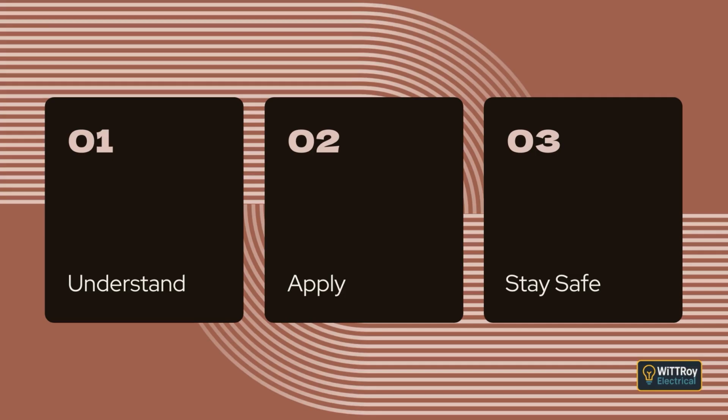Clause 3.9.4.3.2, Protection required. If wiring passes through a structural member, or is fixed in position within 50 mm of the surface to which roofing or wall material is attached, one of the approved protection methods must be used. Clause 3.9.4.4, Protection methods. Where protection is required, the wiring system must either have adequate mechanical protection, or be enclosed in an earthed metallic covering, or be protected by an RCD with a maximum residual operating current of 30 mA.